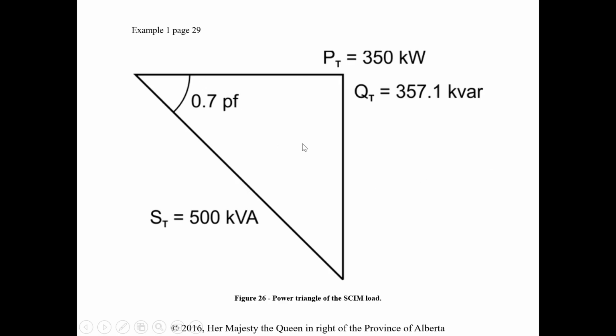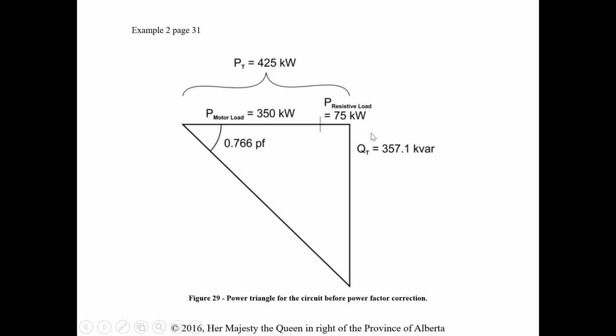So then they go through and just do some examples of power factor correction. Again, I know you guys have gone through this, I think, for 3 years now. So I usually go through this on the board. I went through one in class the other day. So go through those examples. They do a solid job of going through and telling you how to do the power factor correction. They include some efficiency calculations as well for our motors, whether induction motors like squirrel cage, or synchronous motors. Again, don't forget that it's still a motor. It does have watts, even if it's a synchronous motor. The difference is just that the VARs are leading.